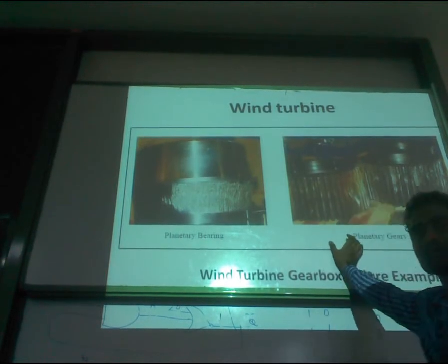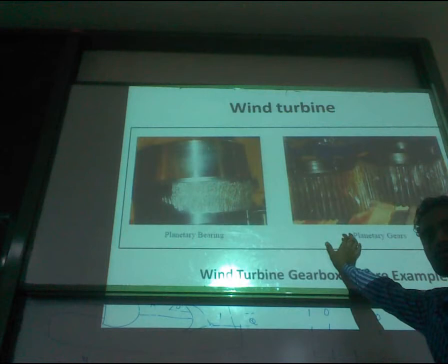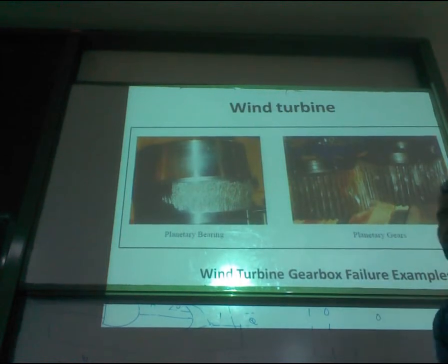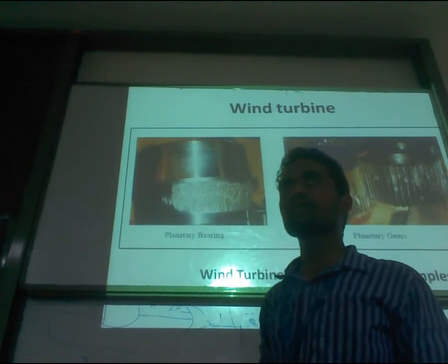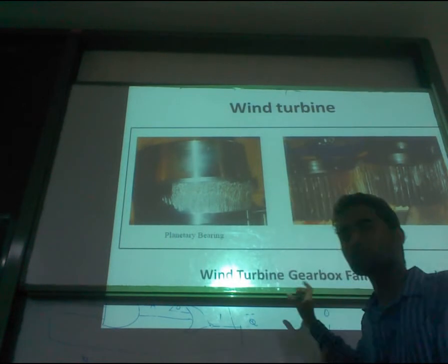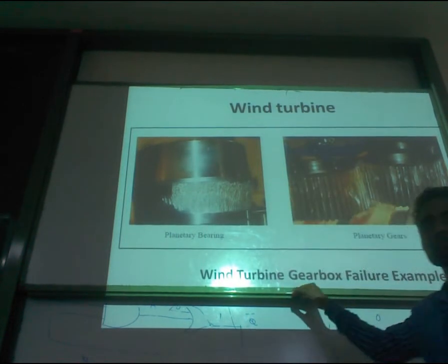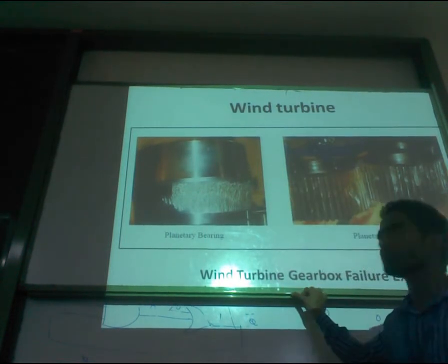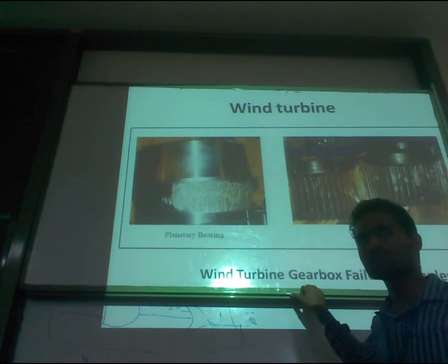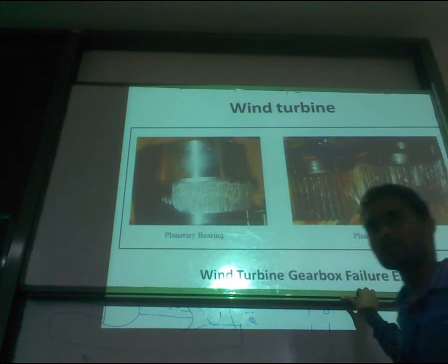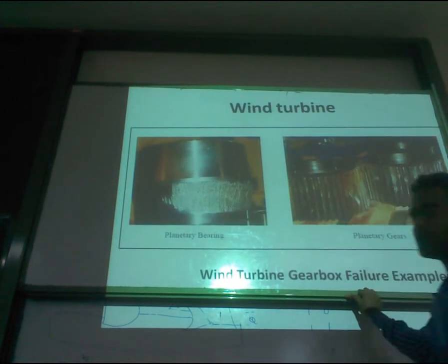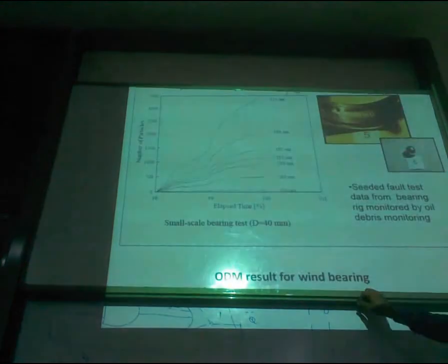That count clearly indicates whether the engine is going to fail. If the count of oil debris reaches a certain level, it indicates that your engine is going to fail. At that stage, we can stop the engine and replace the gear, bearing, or whatever component is damaged, so that it helps to monitor the engine performance.